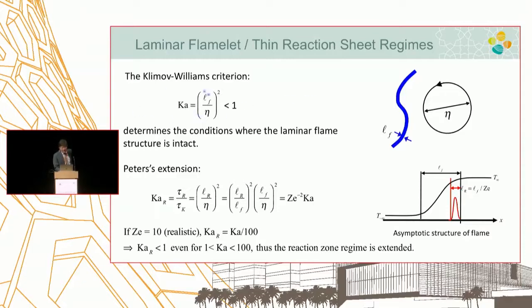So that's the original threshold of determining whether you can treat the turbulent combustion to be more flame-like versus more distributed. Some years later, Peters argued that... Norbert Peters, who passed away, brilliant scholar, theoretician, he is coming from the flamelet school.